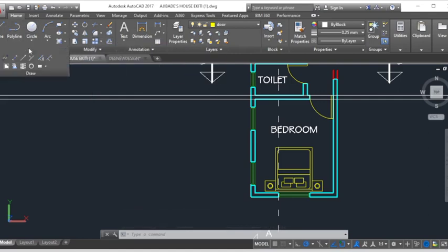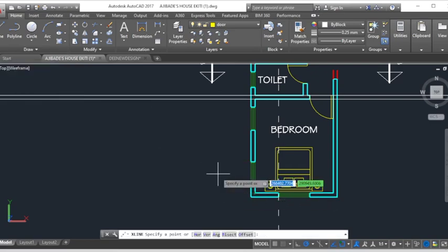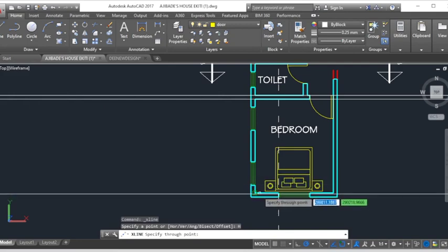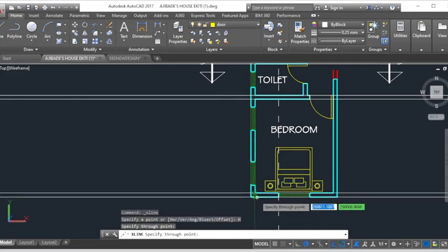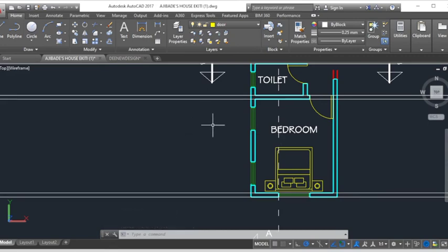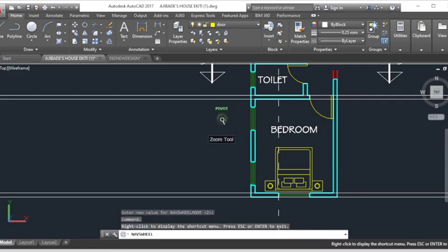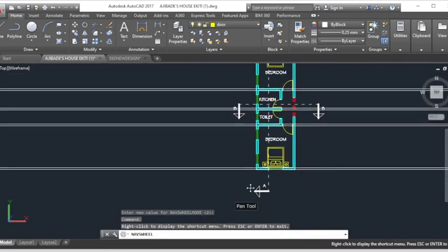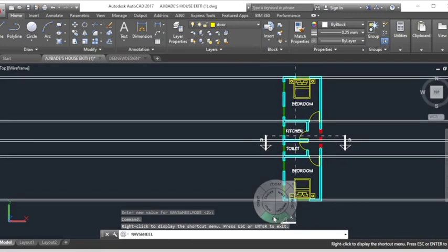So from here we'll pick back our construction line again. Then horizontal, which is H, enter. So I just pick from this point, then this point. After that has been done, also check if we have doors or windows cutting across, just to be clear. So check out for those as well, or beams, just for specification's sake, or stairs.